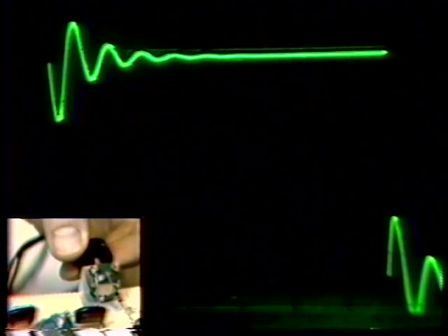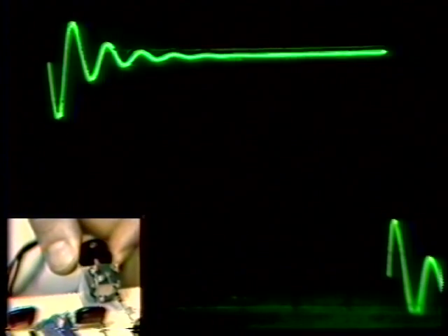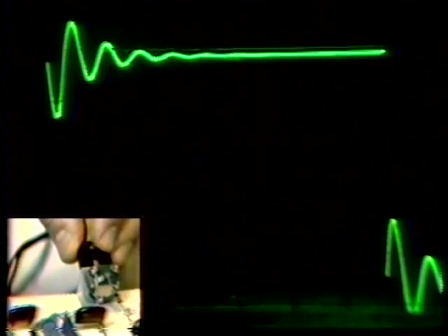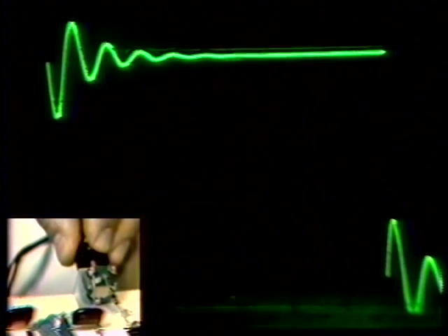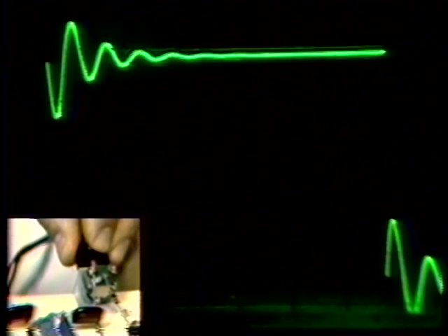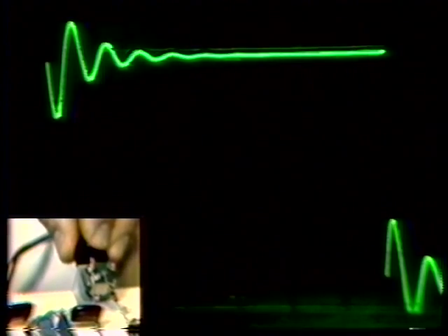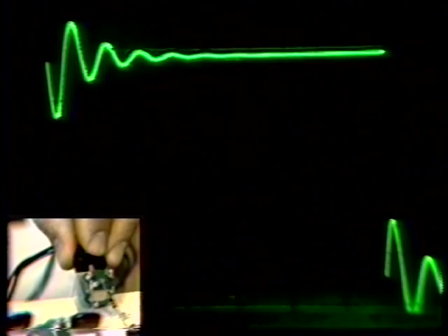All right, here we have the square wave response of our rejection amplifier with the lowest value for A0 that our system allows. We can now begin to increase A0, and we'll see a picture that's very much like the one I've drawn on the blackboard. As we go to progressively larger values of A0 for the step response, we find that the step response, as I indicated it must but didn't draw very well, goes to the final value initially, and to the final value, of course, for very long periods of time after the step's been applied.